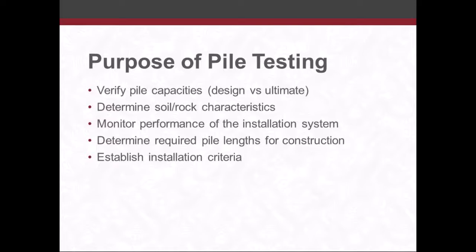We want to determine the required pile lengths for construction, especially for large projects with a lot of piles. If the piles go deeper than what they're planned on a large project, that could result in a large cost overrun. So it's sometimes important, especially on the very large projects, to do some pre-construction testing to determine what the actual pile lengths are going to end up.